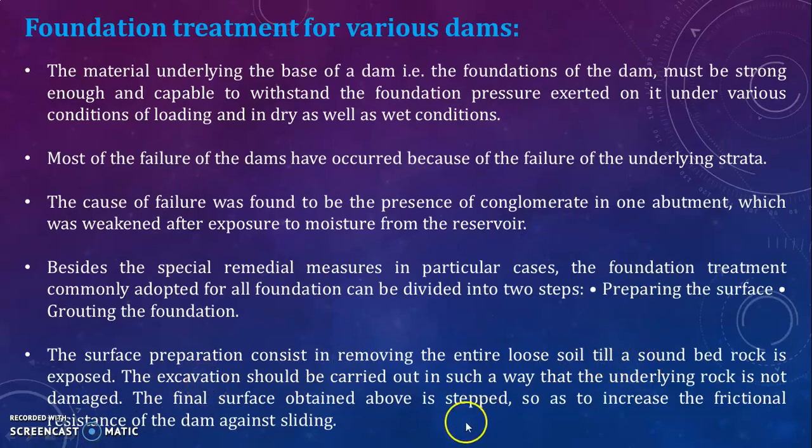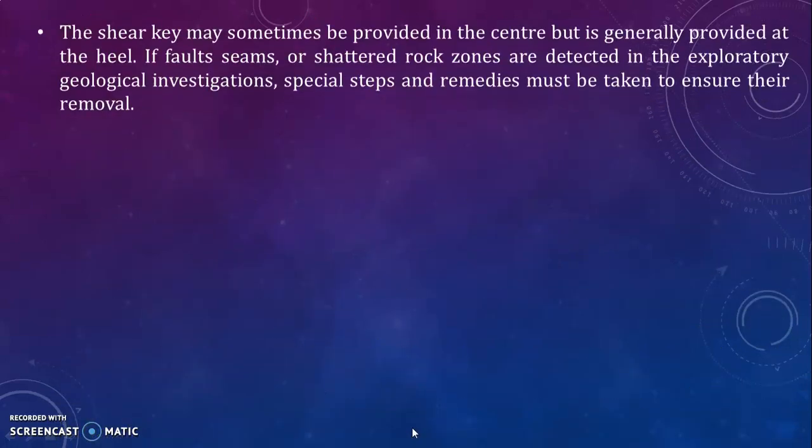The excavation should be carried out in such a way that the underlying rock is not damaged. The final surface obtained is stepped so as to increase the frictional resistance of the dam against sliding. The shear key may sometimes be provided in the center but is generally provided at the heel.